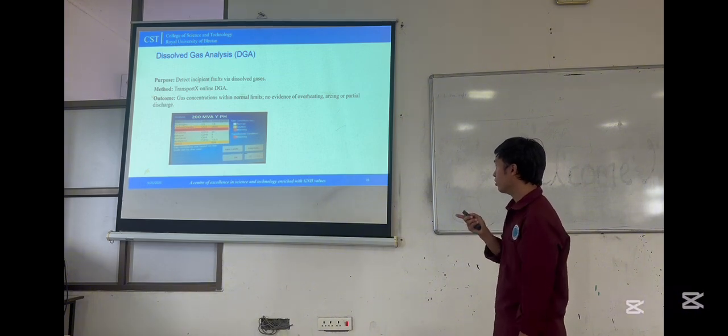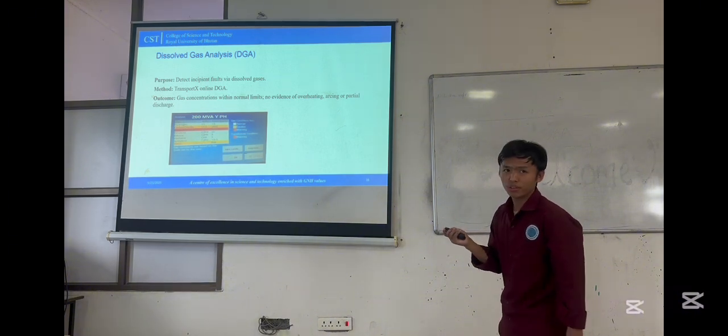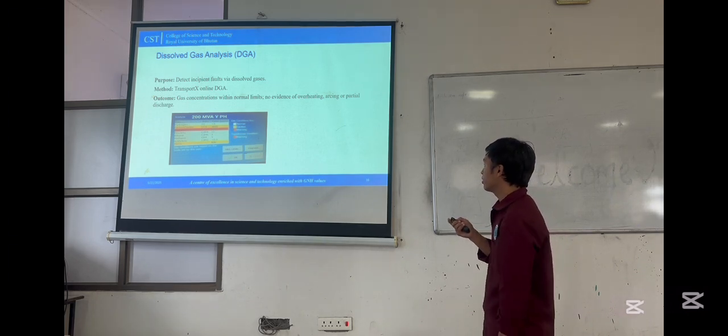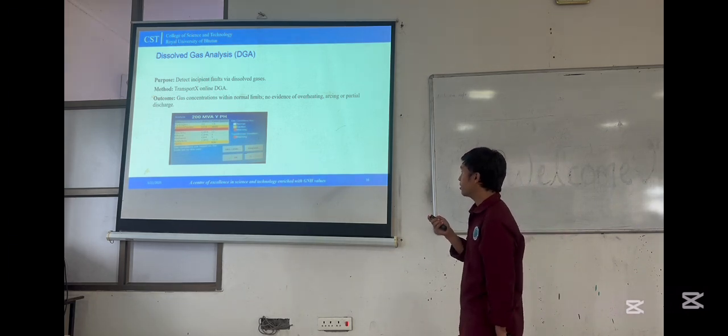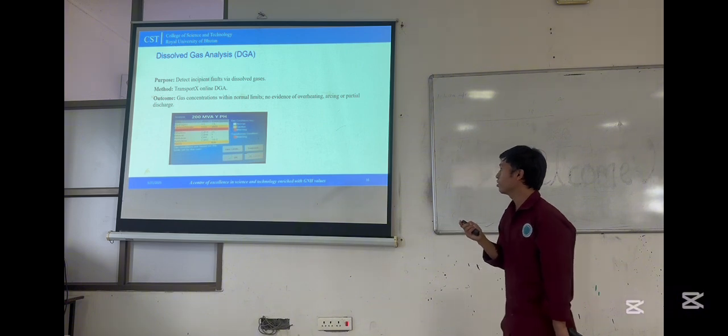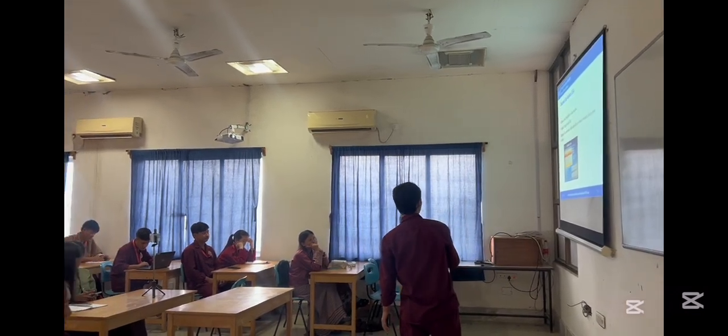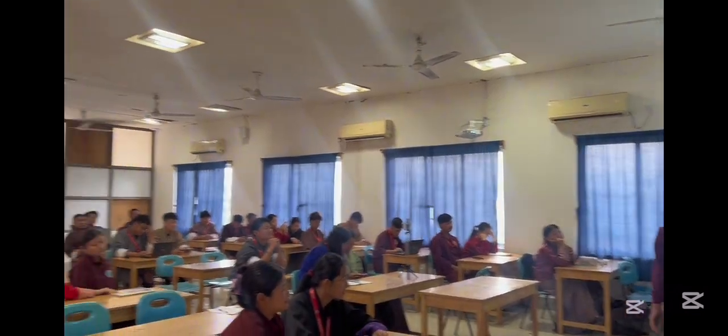And the outcome of this result from the Malwa substation is that the gas concentration is within normal limits, with no evidence of overheating, arcing, or partial discharge. And these are the results.